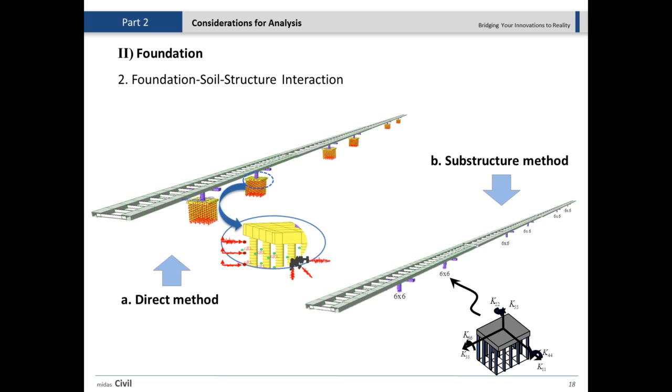By that I mean, for example, if you have one kip force applied on the structure and, let's say, 1 inch of deformation on this part of the substructure, you have to have exactly the same. You have to have exactly the same 6x6 matrix to show exactly the same amount of displacement. So it's challenging to calculate those 6x6 matrices, which are a good representation or a good substitute for the entire pile group.